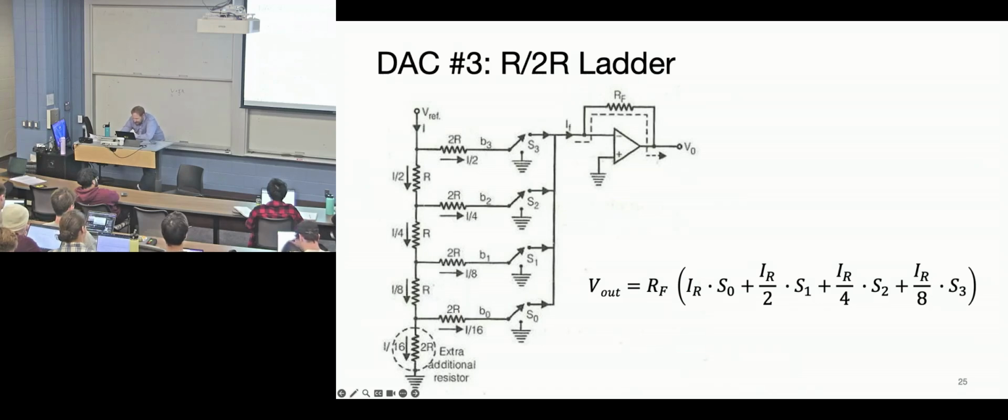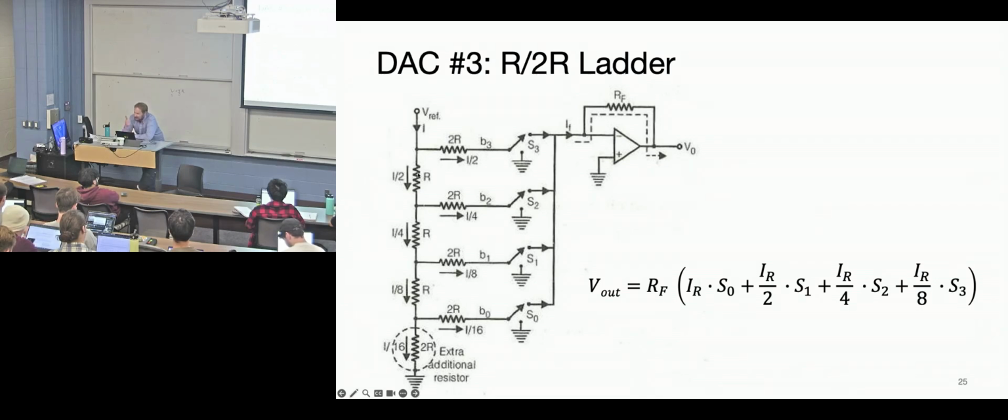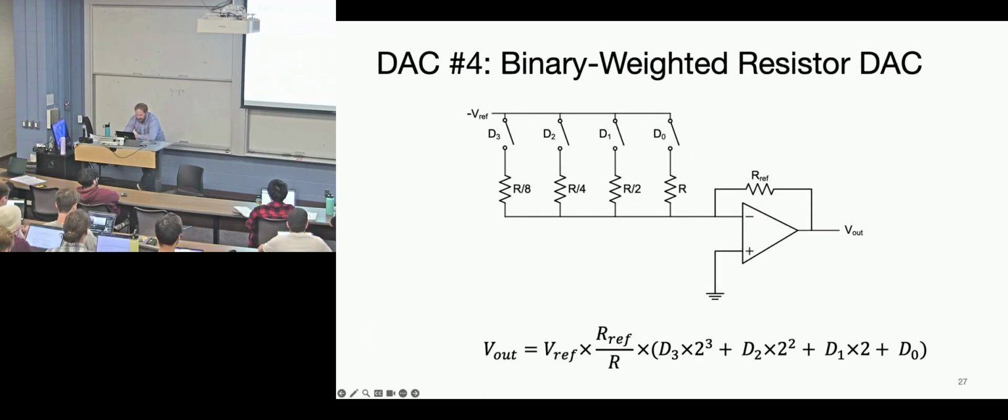And this is the binary weighted. So the trick is the number of resistors, right? Here I have R and then 2R, double that value. And here I have fewer resistors, but I have to make more ratios of those resistors. Before, I only had to have 2 resistor sizes: a resistor that's R and another resistor that's 2R. That's all I have to make in my design and wire up. And the chance that I'll be able to make those without a lot of process variation is pretty high. But here I have to make all these different resistor values and make sure that each one's correct.